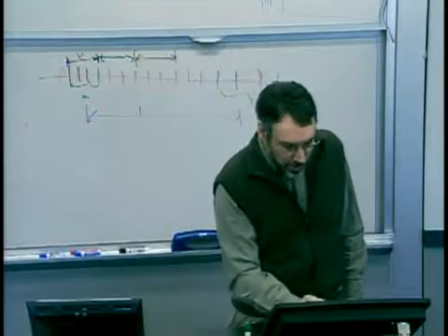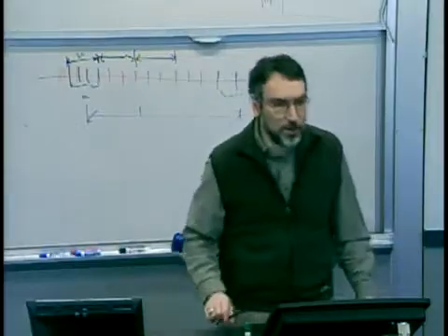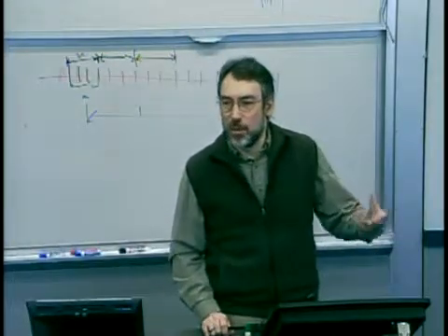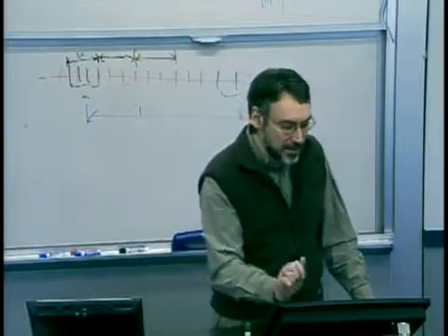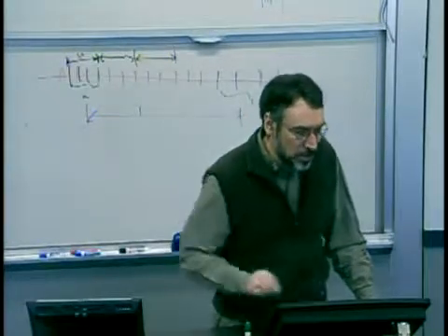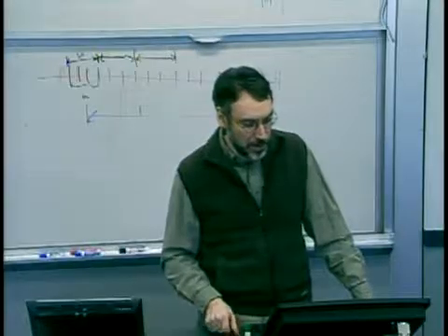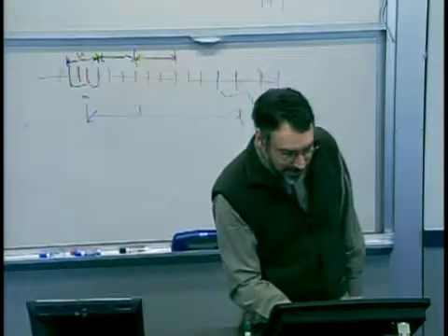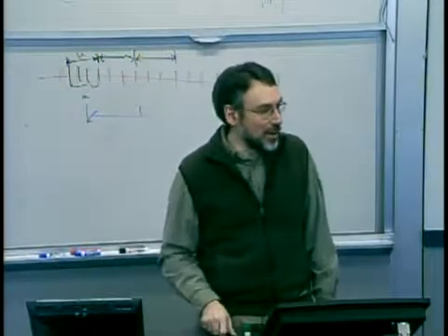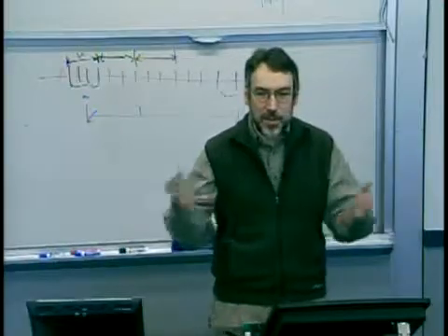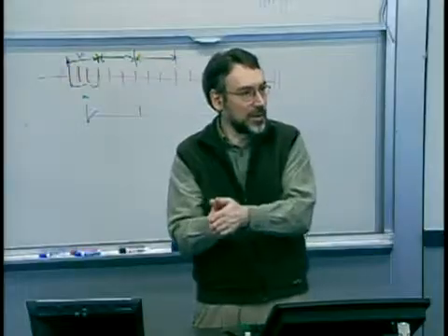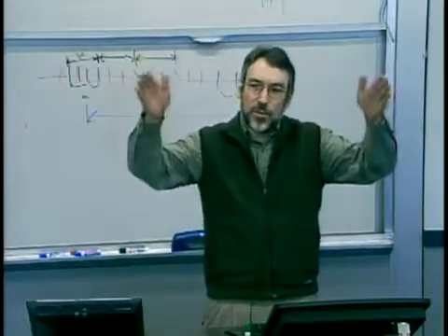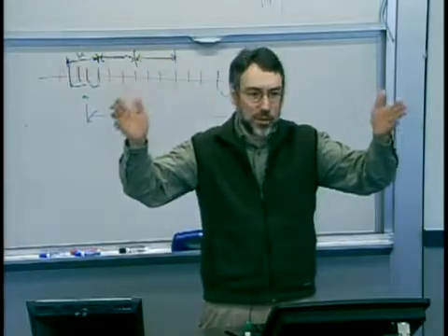The further I get away from x bar, I penalize more and more, not just in a linear fashion, but in a square fashion. And then I have some normalizer or some constant out front. What this basically says is you really want to be on target. So the more of your parts that are right close to the target, the lower your loss function is. And the further away you get, the worse and worse things are.